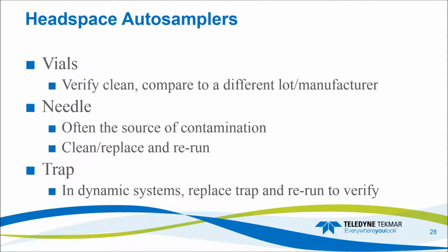So the vials, again, verify that they're clean. Use vials from a different lot or a different manufacturer. Rerun. If you see improvement, that's your issue. If not, we want to look at the needle.